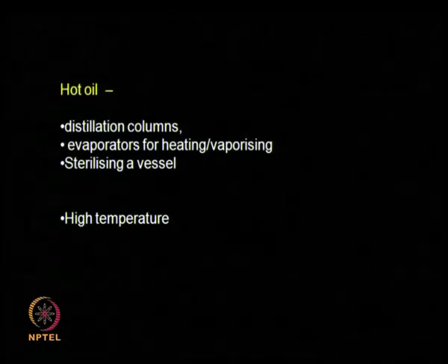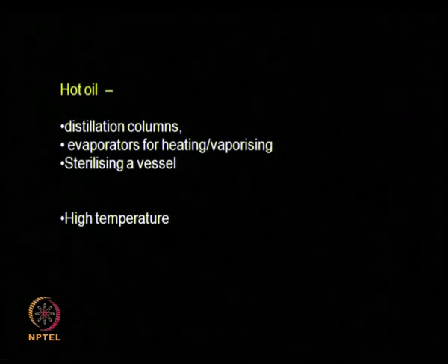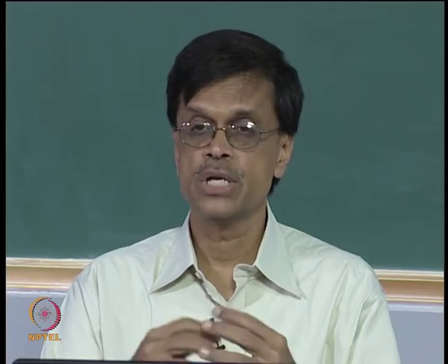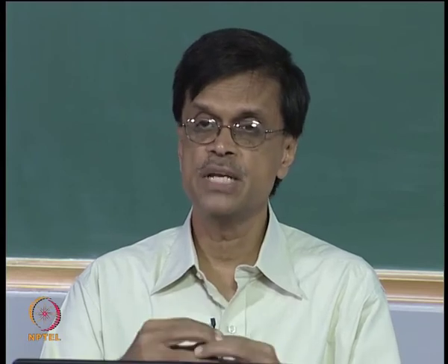So these are some of the very important utilities in a manufacturing plant. The air, maybe the nitrogen, steam, then cooling water, sometimes chilled water or even glycol if you are trying to go down in temperature. So all bioprocess manufacturing facilities will have a few of these utilities. So you need to understand how much utility will be required for the entire plant, what is the rate of utility requirement, and what is the temperature desired in various places in the plant.